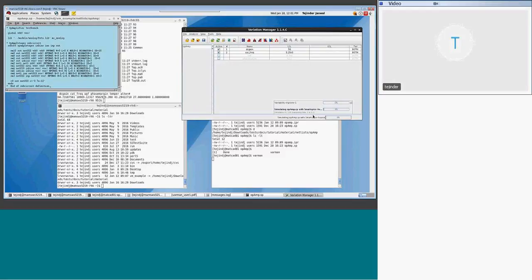Also, if you start with Fast Monte Carlo, as we did, and the tool runs 300 simulations, for example, if you save your project and start another analysis, the Variability Explorer will try to use the first simulation done. In some situations, maybe in this one, it would use 200 from the older run and add a new 100 to complete its budget.